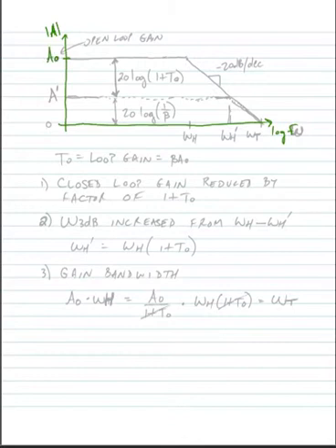So our op-amp has a gain that's A sub 0 at DC. I guess we're plotting this over log of omega, not log of f. At a frequency omega h, the gain starts to roll off. It rolls off at minus 20 dBs per decade and hits a unity gain, or 0 dBs, at a frequency omega t, the transition frequency, or the unity gain frequency, as we call it.